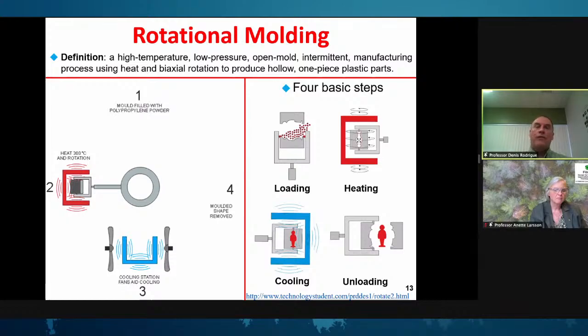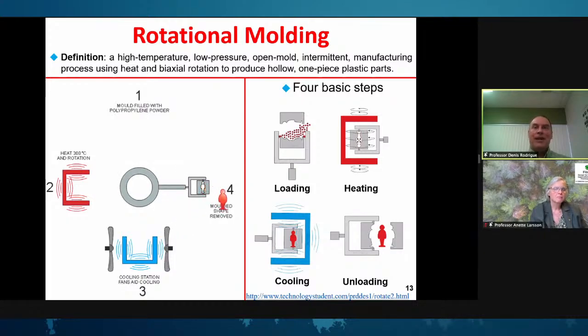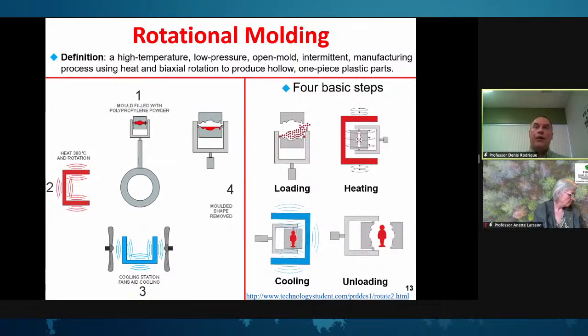So when you talk about the viscosity of the material, yes, there are some limitations. Most people try to have a melt index around 4 to 6. But again, melt index is not really a good indicator because you're actually looking at the zero shear viscosity of your material. For the matrix itself, we have worked with polyethylene, polypropylene, nylon, PLA. Actually, there are a lot of different polymers that can be used as the matrix. But the main parameter would be the molecular weight, because this will control the zero shear viscosity.